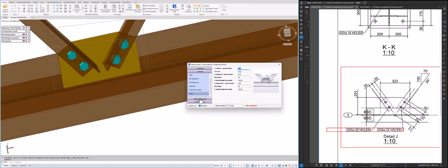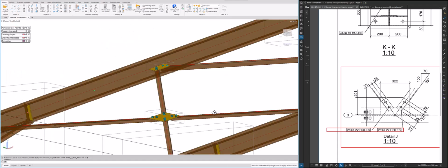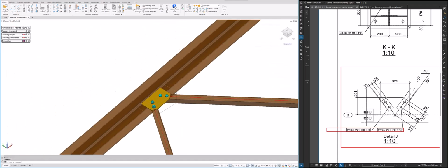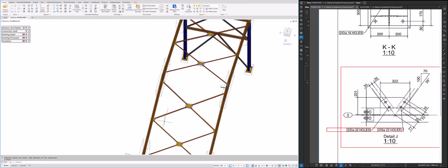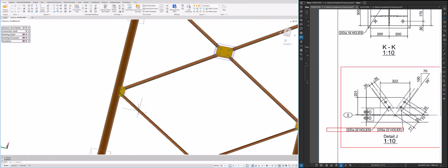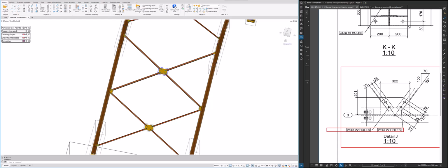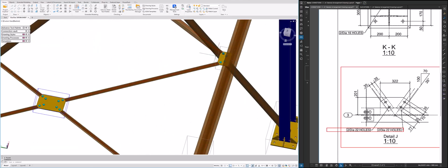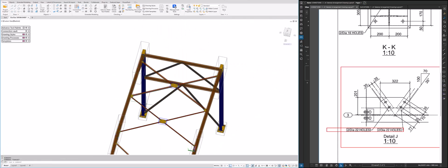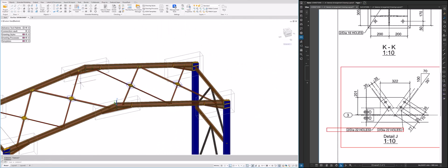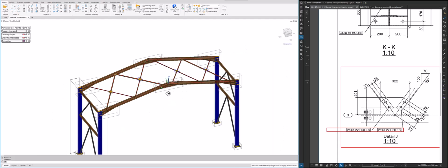Additional connections and stiffeners depends upon the project. We'll see that as we have different projects. So this connection is done. As you can see, that was very easy. So from here, let's just propagate this. Select that, then say propagate joint. Okay guys, as you can see, that connection has been added there as well. It has been added that side as well. It has been added at this connection as well. So guys, we are done with the roof brace connection for this tutorial.